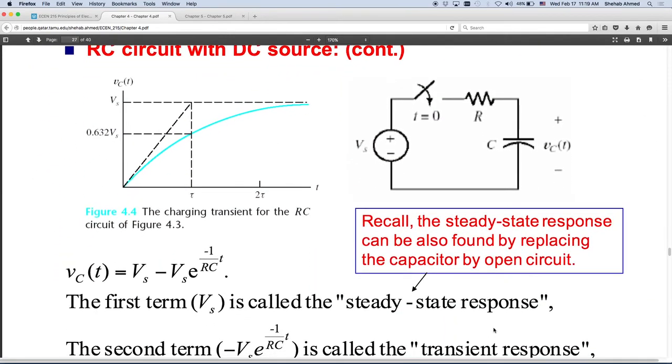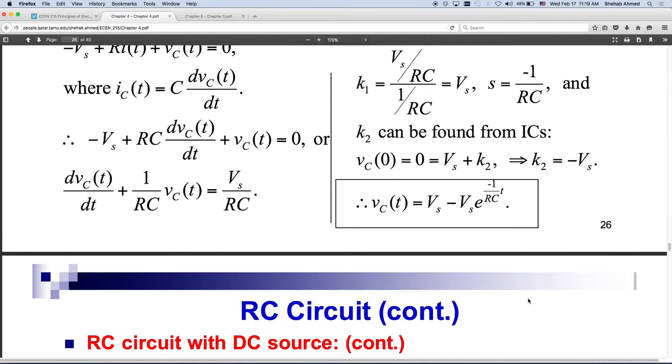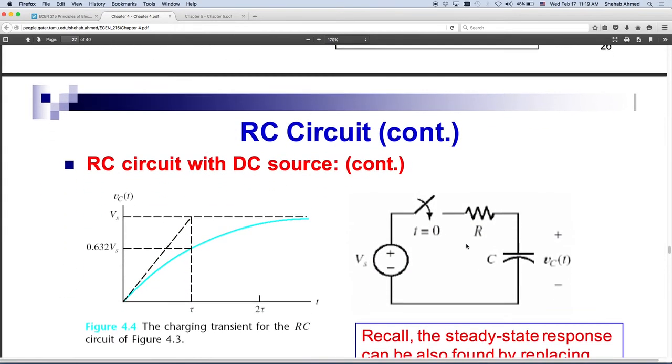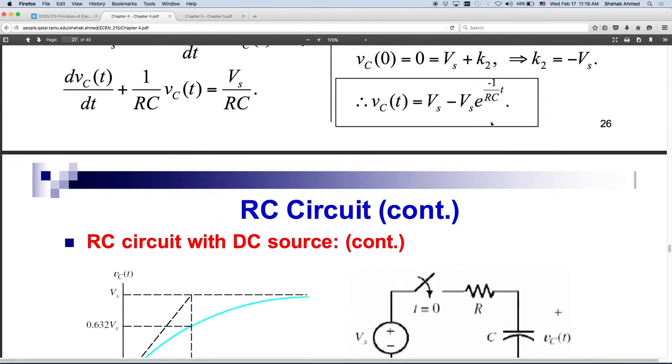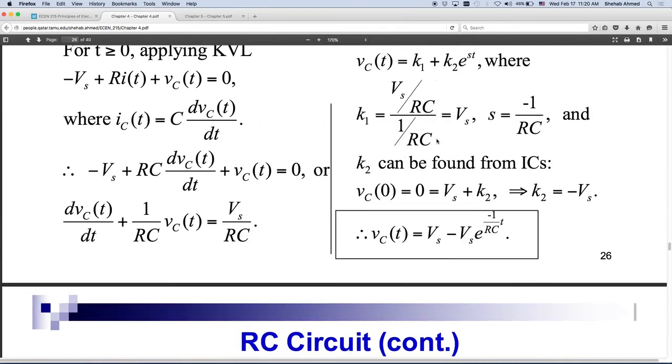Again, current through the capacitor will be the differentiation of that. In this case, we start with a voltage of 0, and this is a decaying exponential, but with a minus sign, so I flipped it, so it's a charging exponential starting from some initial condition. The initial condition happened to be 0. The value for this decaying term is eventually 0 as well, so what will I finally reach? I will finally reach Vs. And it makes sense.